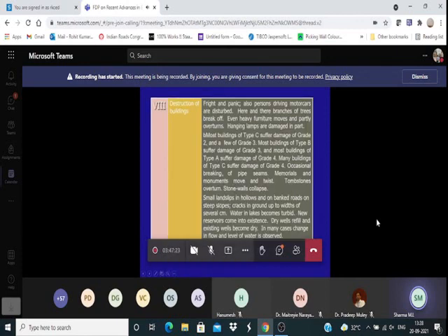Suppose I go to intensity 8. Now here you will find that most means around 90%. Type C means reinforced. Grade 2 means a little more than grade 1, I mean, a little more cracks. And few of grade 3, even much wider cracks.